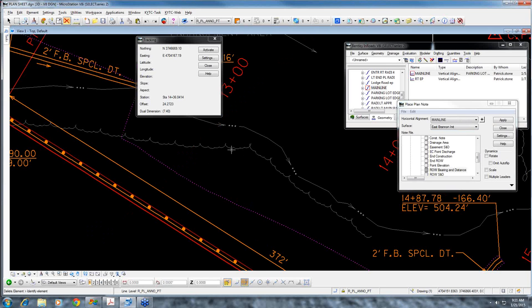And you can also do northing and easting. You just type in any equals and then your coordinates. And you can put elevations on those too, just by adding it to the end of the northing and easting. And that's what the brackets would indicate on that list I showed you previously, that you can add different commands to it.